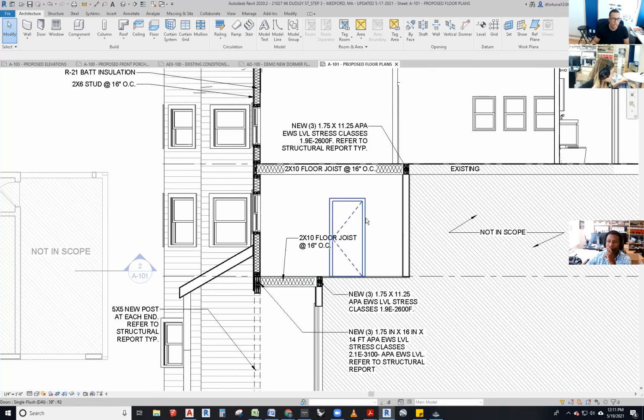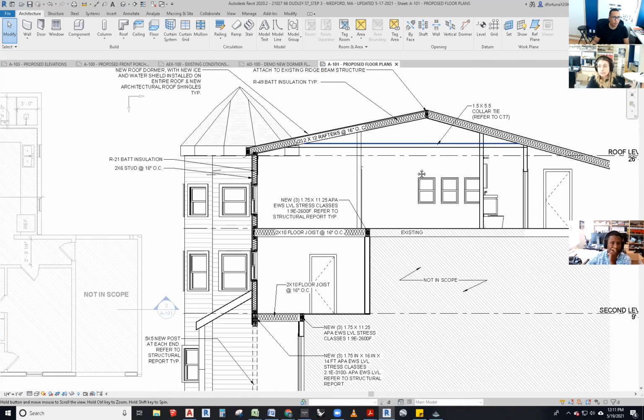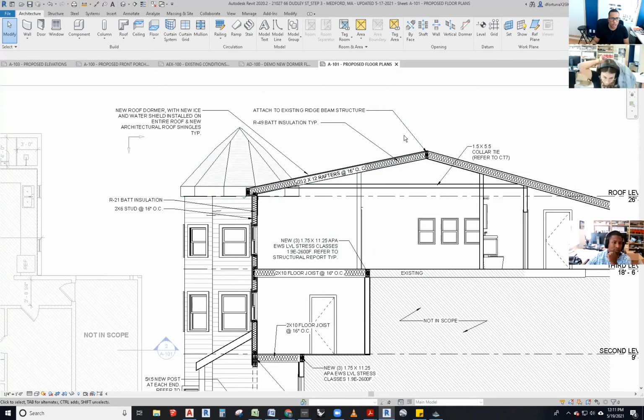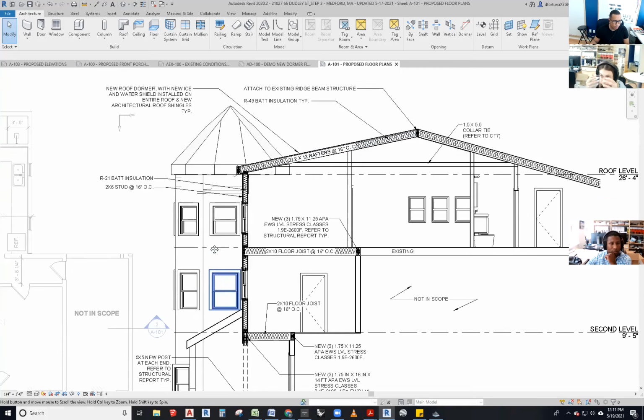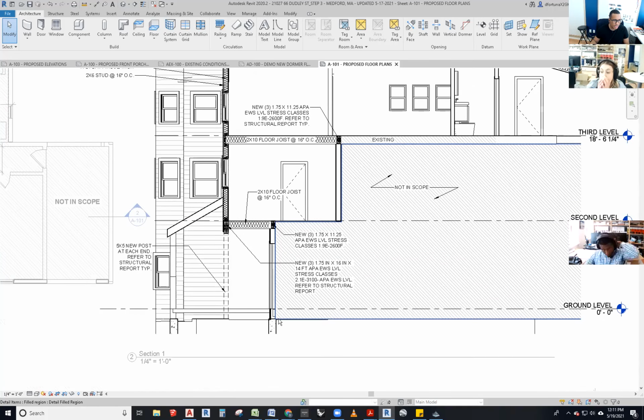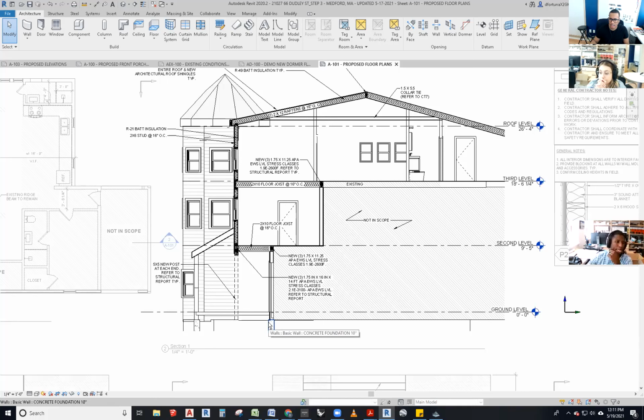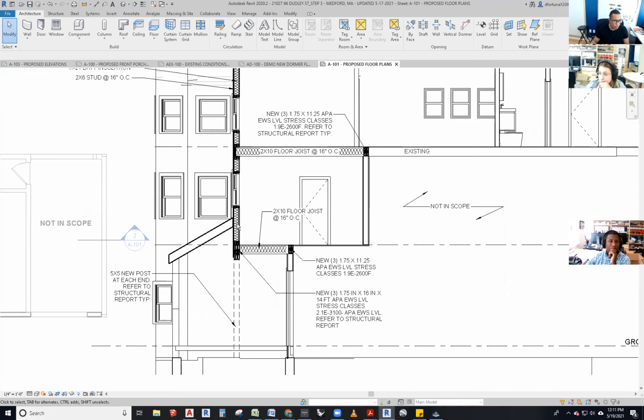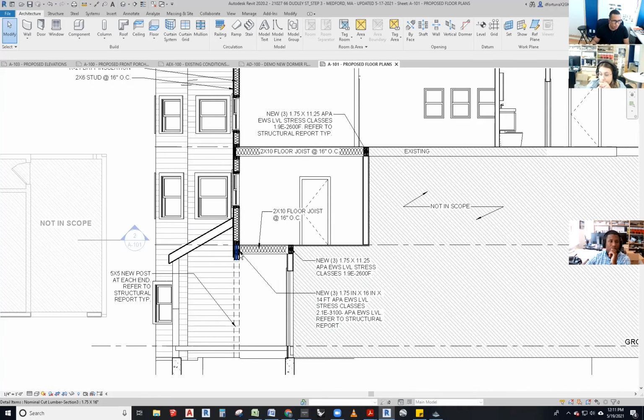What's the learning here? Well, the project started with the idea that we were just adding a dormer, extending a roof. In turn, we were just going to be sizing these roof rafters, connecting the existing roof rafters in here into this existing ridge beam, and probably sizing a new ridge beam, and this all was supposedly going to land on this wall, which is an exterior wall and has a foundation. That's not the case. It's not landing on that wall. It's floating. So because it's floating, we picked up that we need a beam here to support it.